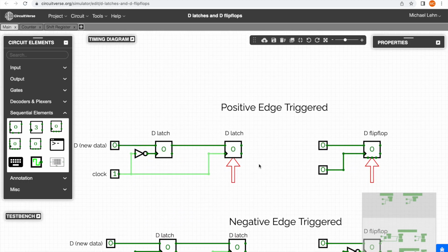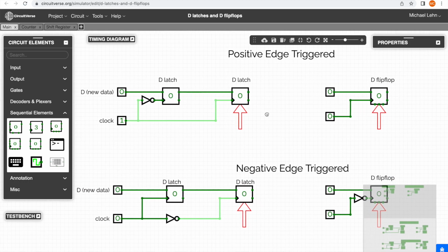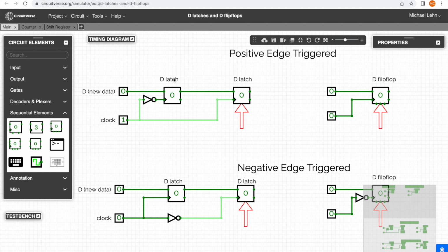And actually you already saw how a D flip-flop can be built with D latches. You saw in these previous examples, where we, for example, were building a counter, that we often used two D latches together and a NOT gate. And actually we discovered there are two variants that are helpful for this counter example. Basically you can think of this NOT gate doing the job of checking whether the clock was previously 0 and now is 1, or the opposite, whether it was previously 1 and now is 0. And in this variant you have a behavior that is the same as in the D flip-flop case.